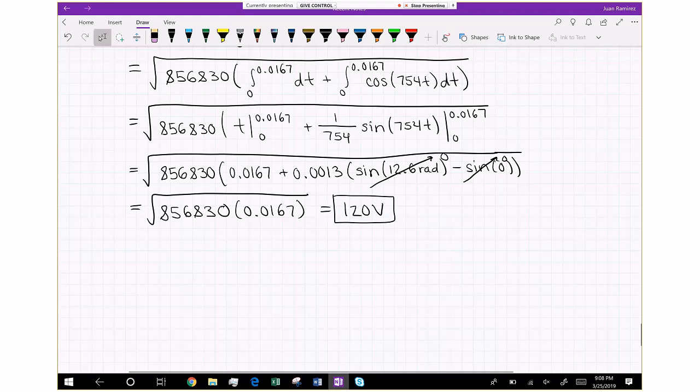When you go into industrial, you typically have 120, 208. They use 3-phase. And then the other standard is 277, 480. So the 120, 208, 120 is a line to neutral voltage, 208 volts is the line to line voltage for 3-phase. And then the 277, 480, 277 is line to neutral, 480 is line to line.